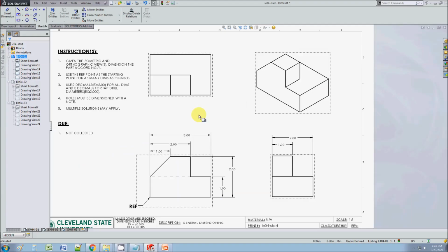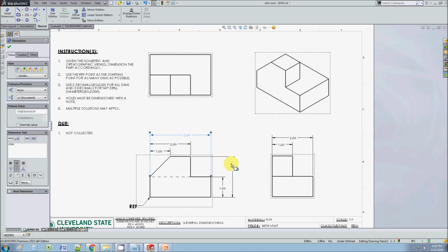So in this example, that's what I'm going to do. They're going to start with an oversized block, meaning I need the width, height, and length. Okay, and I hold control to select them. Then they're going to mill this little chamfer here. And to do that, they need to know this position, that position, which they do. They know this position from here, and they know that position from there. What I'm essentially doing, I'm looking to see if I have the Cartesian coordinates for each of these points. What I mean by Cartesian coordinates, I mean the x and y position. If I have the x and y position for each of these points, then I have no missing dimension.